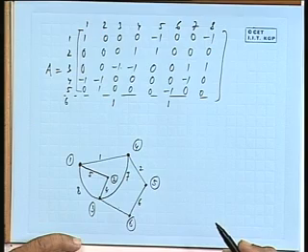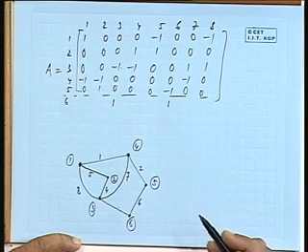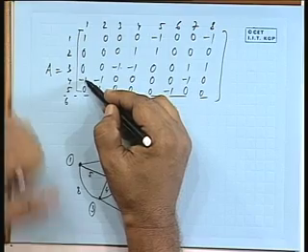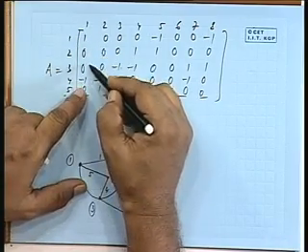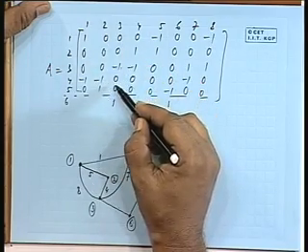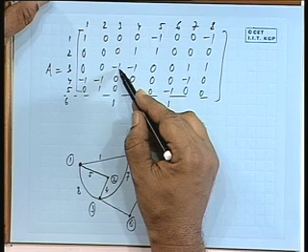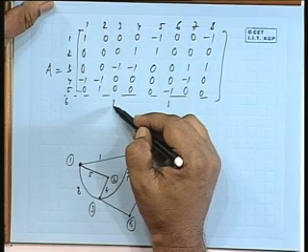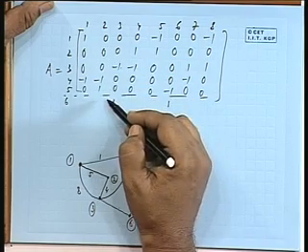How do we decide that the reference is there, if the sign is plus 1? See, in each column there can be only two elements, one plus 1 and one minus 1. To find out where the ones are missing, there is only one element here, plus 1 is missing. So that will be connected to the 6th node which is missing, the reference. But it could have been connected to another node also in the same column. Possible.